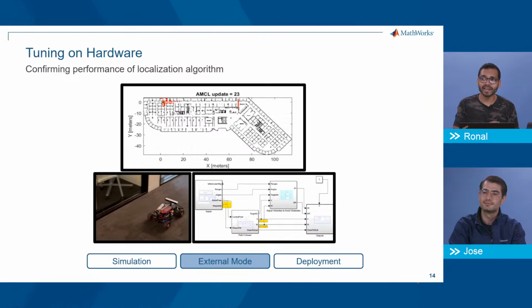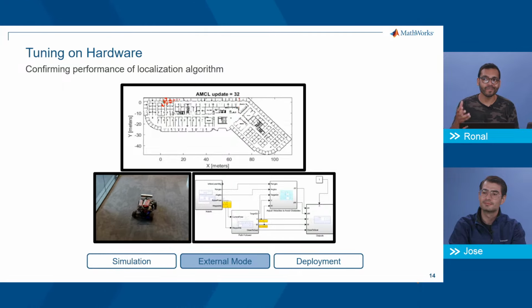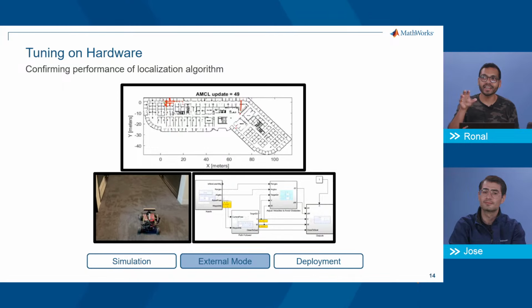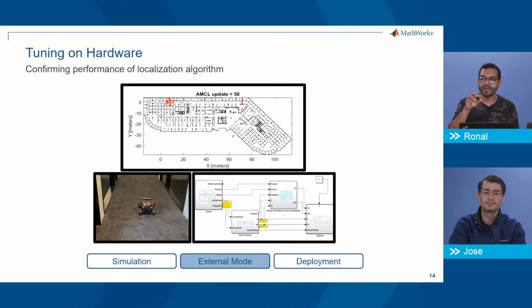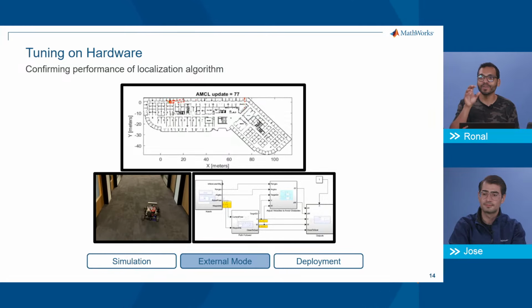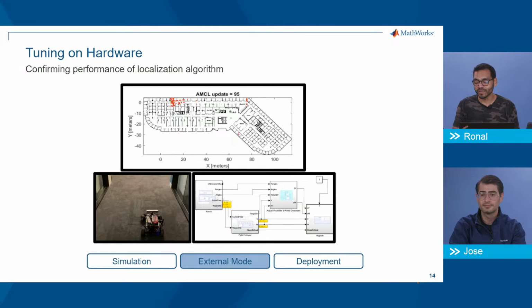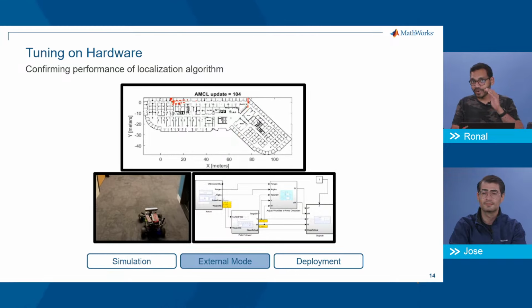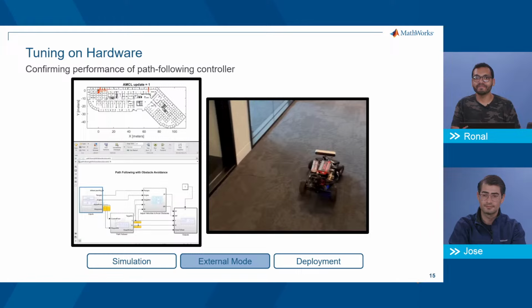Because you're working with MATLAB, you get access to a lot more functionality. So here you can see on top, I'm taking my LiDAR scan, and I'm actually plotting it on top of my map. This is using Monte Carlo localization. So I'm using that LiDAR scan to relocalize my robot as it goes through the environment. Pre-built, ready for you to use if you'd like.